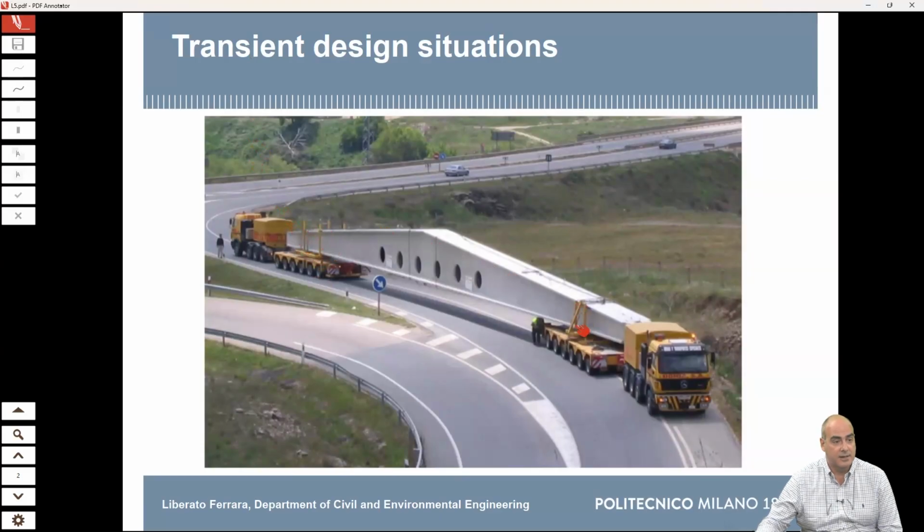As you can see, look here, the beam is basically constrained here and restrained here, okay? So if you think from a structural design point of view, you can say, okay, this beam is supported on one end on one of the tracks, on the other end on the other track, and it's simply supported. Most likely it is the same scheme that the beam will experience when it is installed. It will be positioned on 2 columns. There will be some bars, some pins coming up. It will be connected, and you can consider that joint between the beam and the column like a hinged joint.